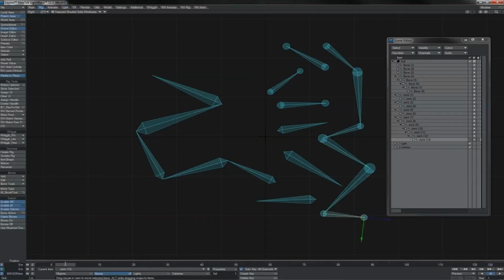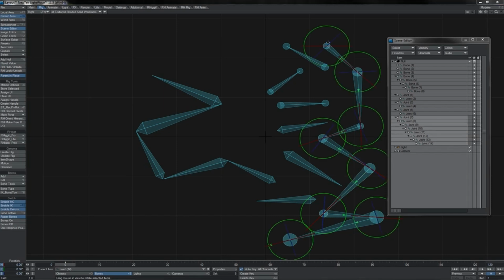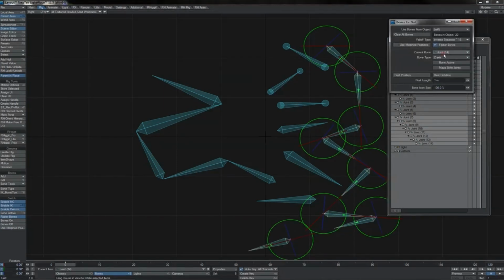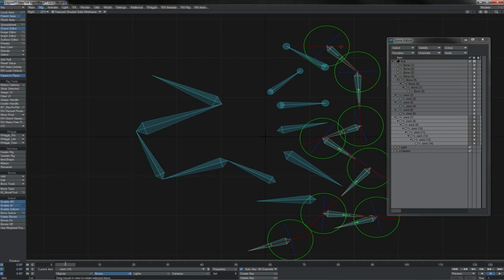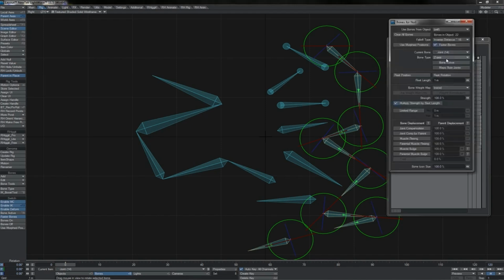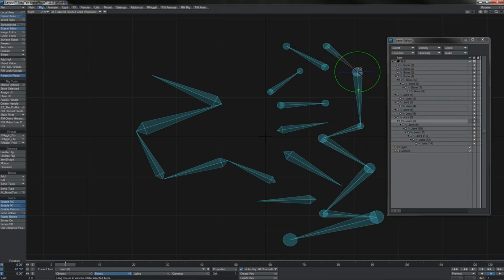One of the important things to notice when using draw joints and draw child joints is that, like Z bones, they will be oriented to one another. You'll notice that if we click this whole hierarchy here and we alter them to become Z-axis bones, their rest lengths are off because they were never set since we were using the draw joints tool, but you can see that parent points to child, they are all aligned properly. This is important to note, because as we've seen with joints, they don't have to be aligned for their deformer portions to exist.